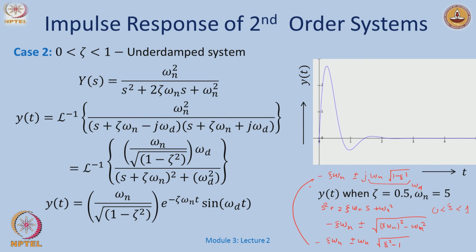Okay. Now, I just want to see the natural response or the impulse response, so I do all the Laplace and inverse Laplace transforms which I learned earlier. I see that y of t is some number, omega n and so on, times an exponentially decaying term, and this guy. I say exponentially decaying because all these terms are positive, and with time it just falls in value and goes to 0.